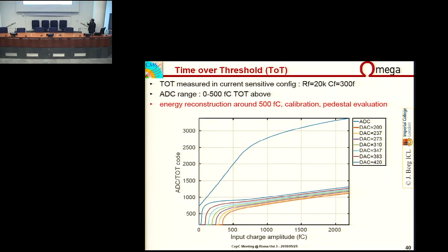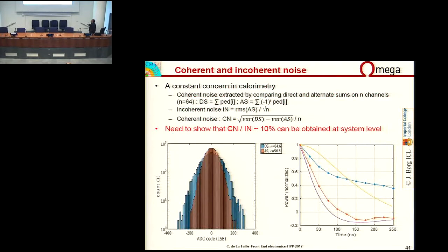One very important thing concerning this HGCal feature is that instead of using a low gain channel, we plan to use a time over threshold technique, because this event will be very rare. So what will be done is we will compare the preamplifier with a threshold, and thanks to that we have information concerning the charge deposited on the preamplifier.